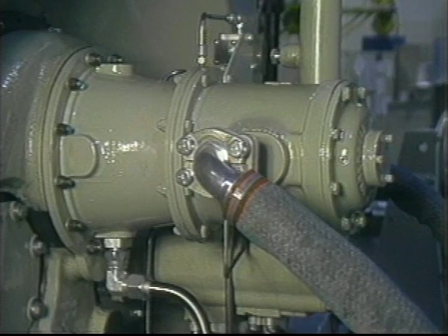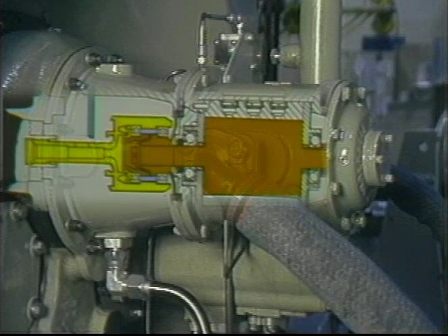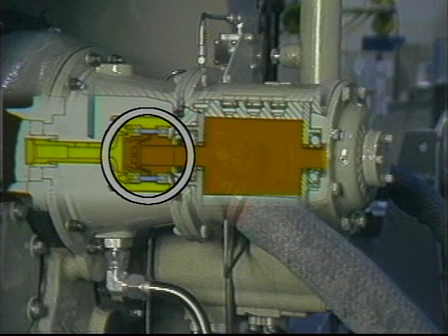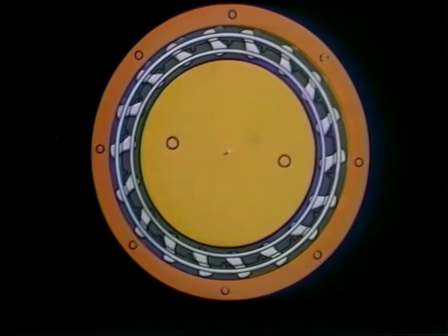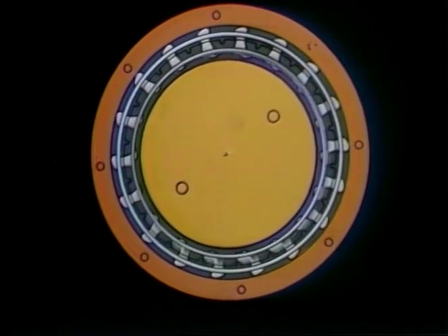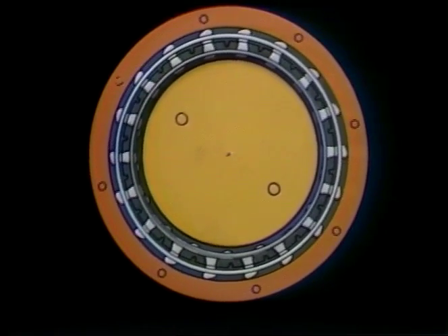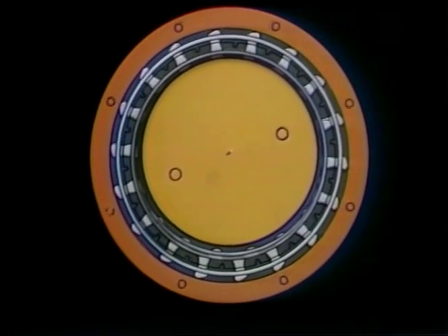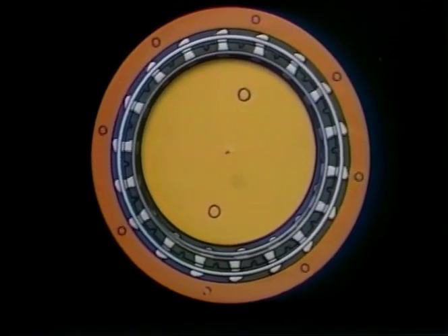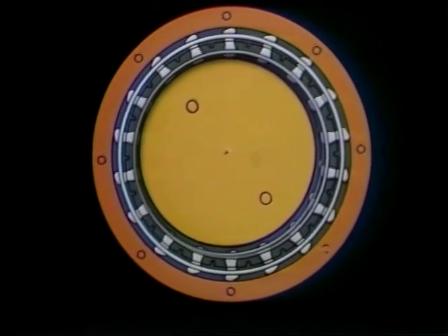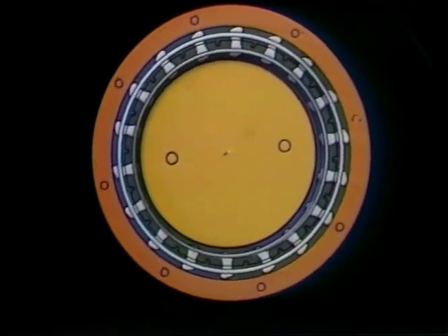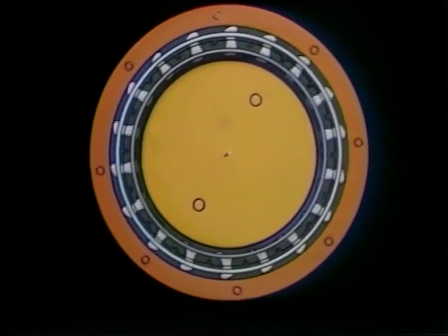The starter shaft is connected to the splined interconnect drive shaft with a sprag clutch. The clutch functions to transfer rotational motion from the starter shaft to the accessory drive shaft, thus creating the initial rotation of the engine. The clutch incorporates wedges called pawls. When the inner race, which is connected to the starter shaft, begins to turn, the pawls will stand up and wedge themselves between the spaces of the inner and outer races. When the engine reaches 60% speed, the start system will be de-energized. The pawls will then lie down and disengage the starter motor.